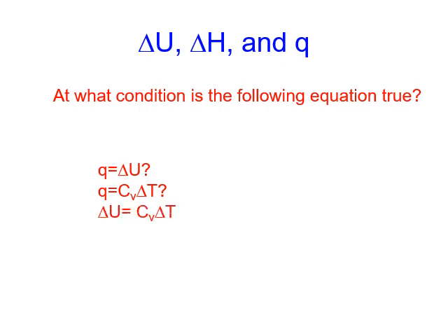So when can you calculate delta U by Cv delta T? Well, if it's constant volume, work is 0, heat is delta U. So this equation is always true, even for non-ideal gas, if it's constant volume. What if it's not constant volume? If it's not constant volume, this equation is still true for ideal gas, because ideal gas internal energy is a function of temperature only.